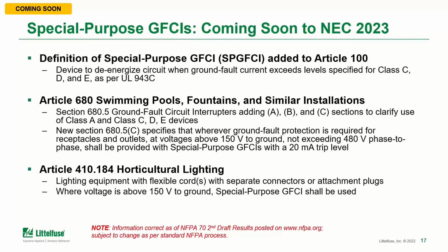Now, one very interesting change in the world of GFCIs is set to occur next year. Special purpose GFCIs have been defined for some time, but they're now on deck to be added to the 2023 electrical code that is still in the works. These comments have passed second draft. They still have some steps to complete in the NEC code cycle process, so I have a disclaimer at the bottom that until it's final, it's not necessarily complete.